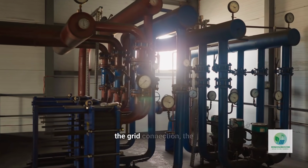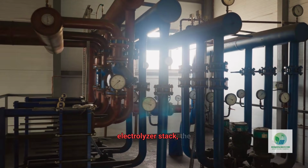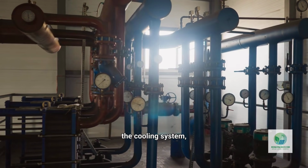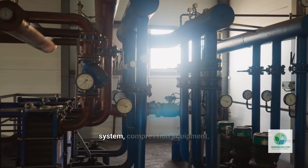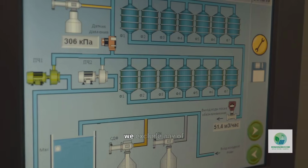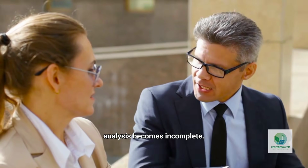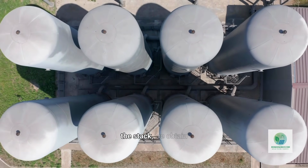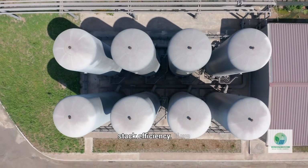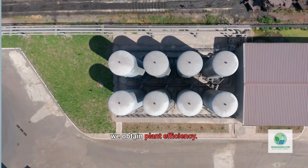Inside that boundary are the grid connection, the transformer, the rectifier, the electrolyzer stack, the water treatment system, the cooling system, the gas purification system, compression equipment, and auxiliary systems. Everything inside this boundary must be included in the energy balance. If we exclude any of these components, our analysis becomes incomplete. If we analyze only the stack, we obtain stack efficiency. If we analyze the entire boundary shown in image number 1, we obtain plant efficiency.